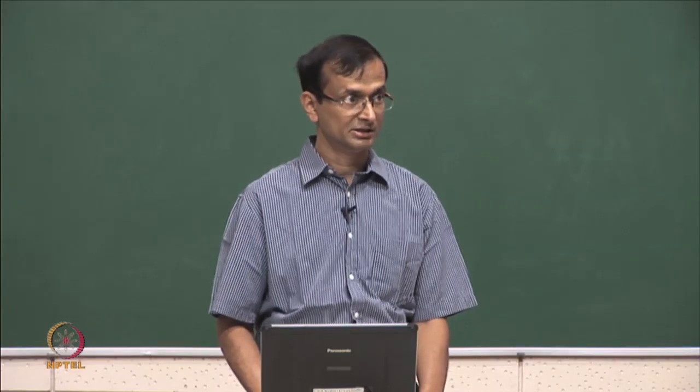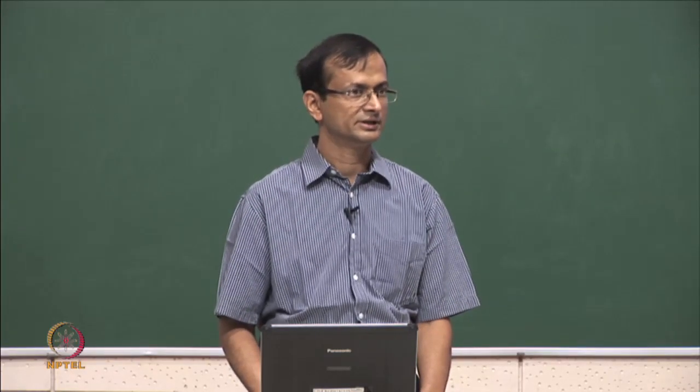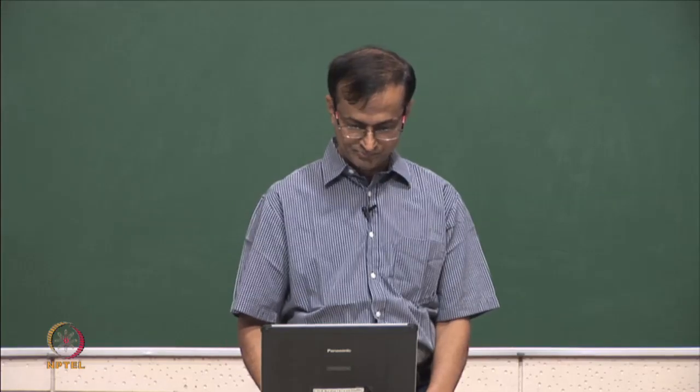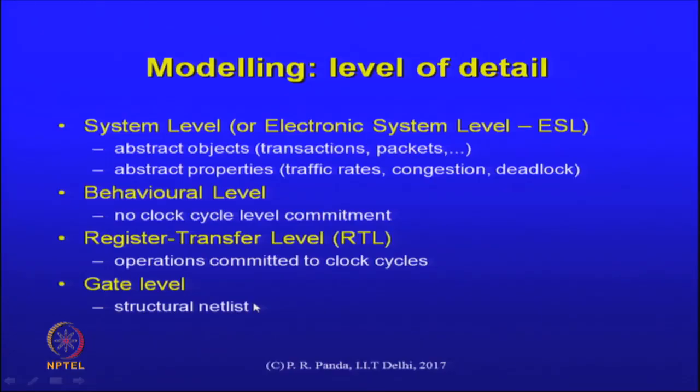It's still an RTL design, but the description of functionality could well be specified in text form. But that is different when you go down further into the gate level of abstraction. That is when you have structure explicitly built in, and you have a structural netlist that actually is a representation of our design.